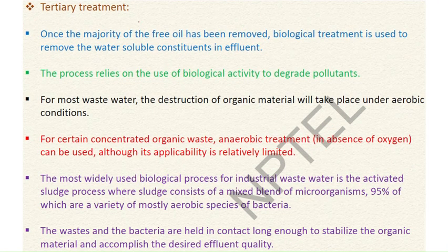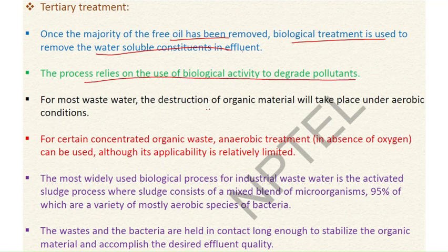Tertiary treatment: once the majority of the free oil has been removed, biological treatments are done. Till now, the solid and oil waste has been removed. That is physical treatment. But in the tertiary treatment, biological treatment is done to remove the water soluble constituents and impurities. Okay. The process relies on the use of biological activity to degrade pollutants.